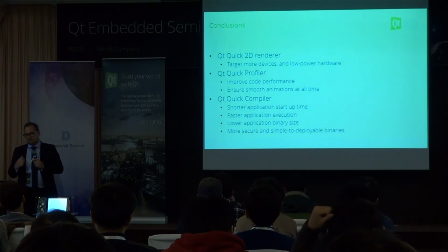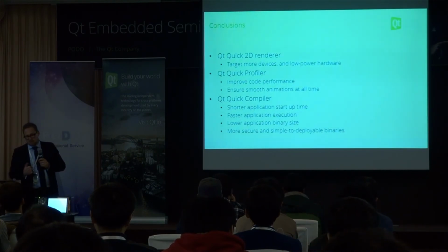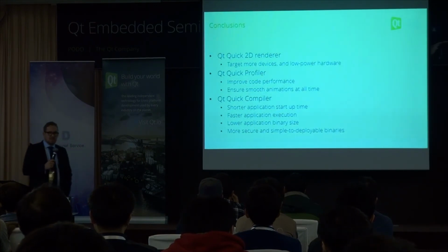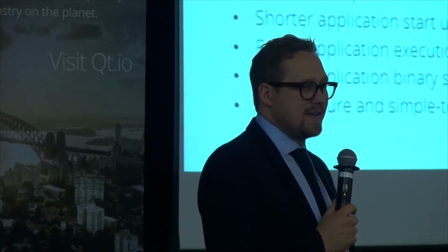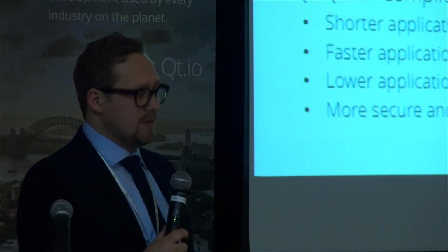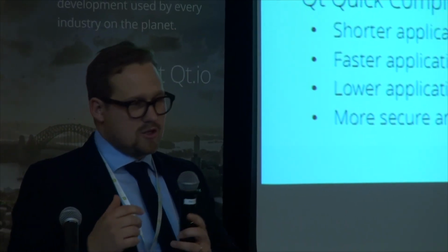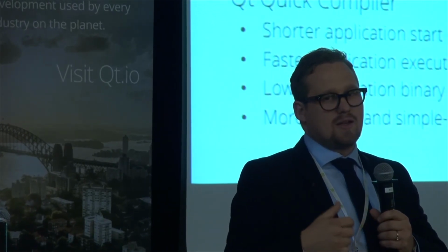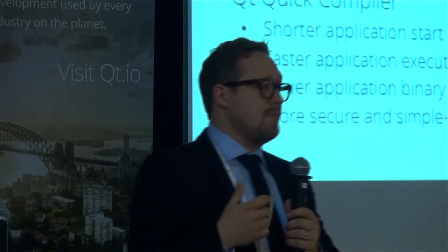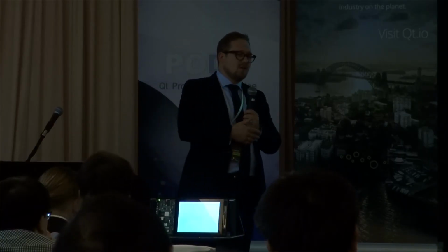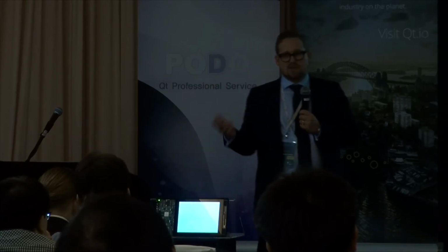Another really nice feature is the Qt Quick compiler. And the Qt Quick compiler is another part of the Qt for application or Qt for device creation package that allows you to significantly improve your embedded application. Standard Qt Quick is going to be just-in-time compiled on your device at boot of application startup. It also means that all of the QML files are readable resources that are easily available.